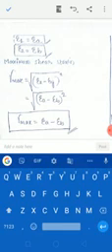If you simplify this, the 2 gets cancelled, you get epsilon 1 equal to epsilon a. Next, similarly epsilon 2 equal to epsilon b. Correct? If you take plus, you will get epsilon 1 equal to epsilon a. If you take negative, that is minus, you will get epsilon 2 equal to epsilon b. Now maximum shear strain, how will you get? Already I have told you, you will take the under root term, that is under root epsilon x minus epsilon y. Wherever epsilon x, epsilon y is there, you can replace by epsilon a minus epsilon b square. So gamma maximum, how can you write? Epsilon a minus epsilon b.